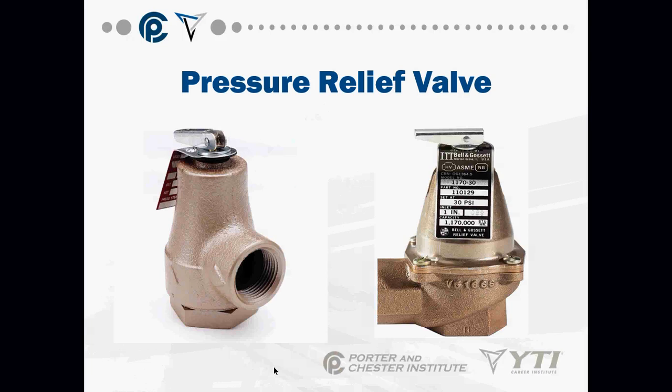Usually a relief valve is a one-time valve, which means that once it opens, it does not necessarily reseat itself properly. And usually we'll call for you to go there and have to replace the valve in its entirety. Otherwise, you're just going to have a leaky valve, and it's just going to make for a bad day for you.